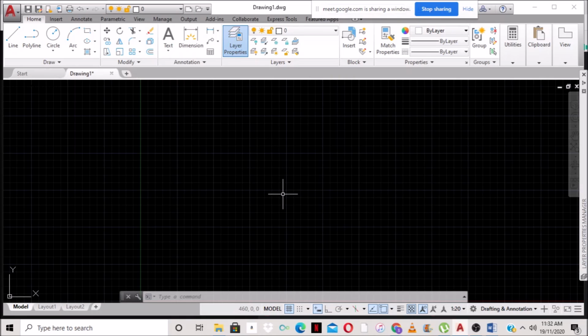What type of drawing are we doing? The camera is what type of drawing? Isometric. So what do we need to turn on in order to draw in isometric? All right, so no one is remembering. So we're going to turn on ISO draft.